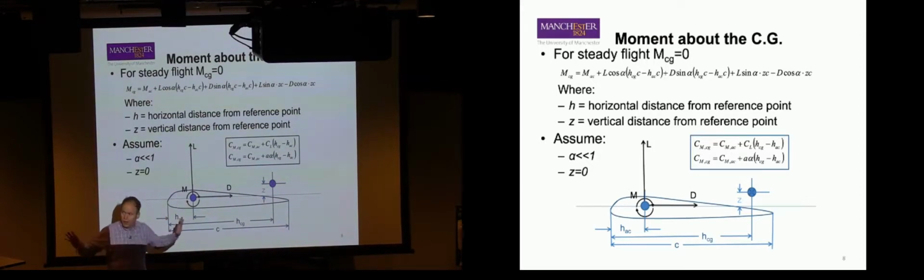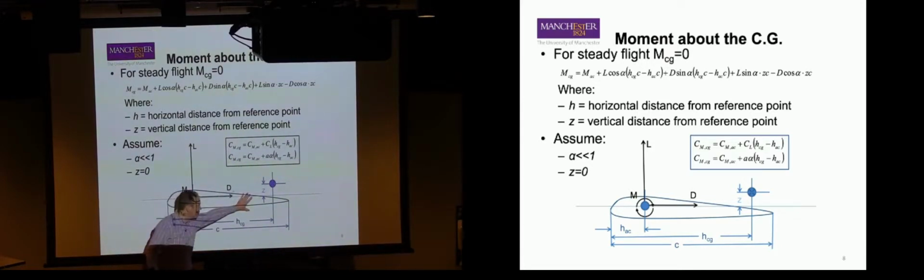No, they were generating no lift, right? So there's no pressure differential between the upper and lower surface anywhere on the wing, but we're still generating a nose-down pitching moment. So where would the center of pressure be? Where would the point where you would have to have lift, but no moment be? Yeah. No, because remember, aerodynamic center, wings rotating. So we're going to now go aft. But how far aft do we have to go? Lift is 0.